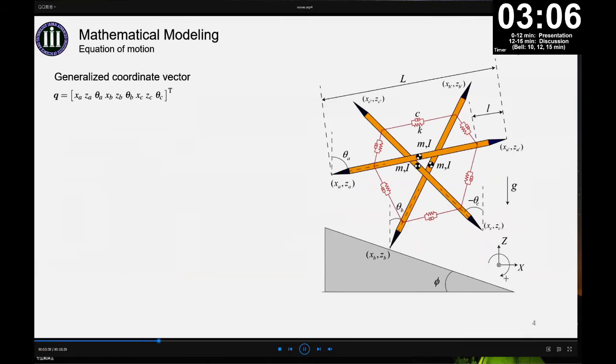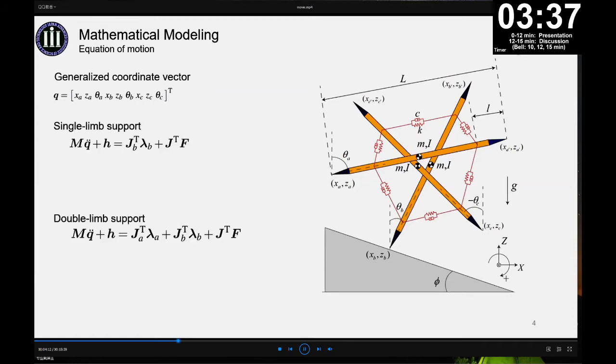According to the passive walking theory of rimless wheel, when the angle between two legs is less than 90 degrees, the energy loss due to collision will not be zero after one step. So, we propose a model that consists of 3 limbs and 6 cables. Such a structure ensures that the angle between the legs is 60 degrees. During the robot motion, not only single leg support but also double leg support will occur. So we give corresponding equations of motion based on different states of motion respectively.